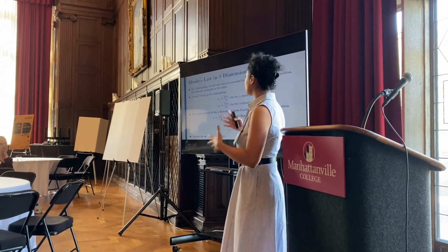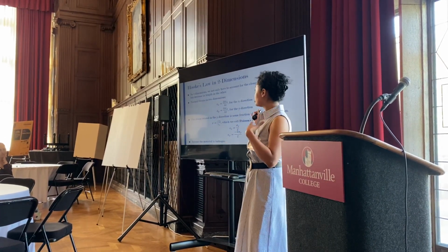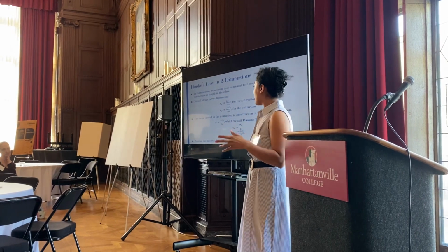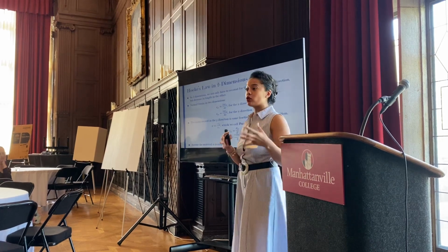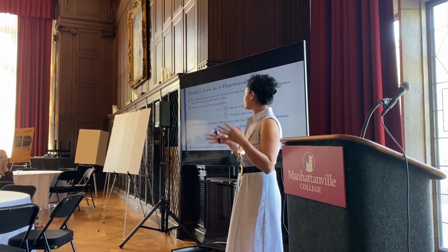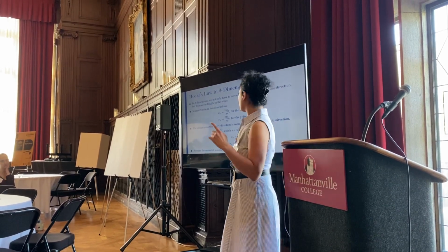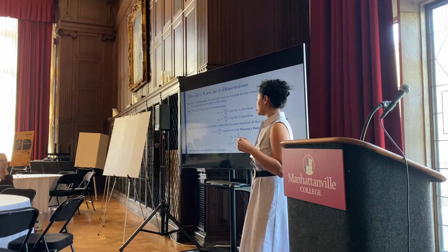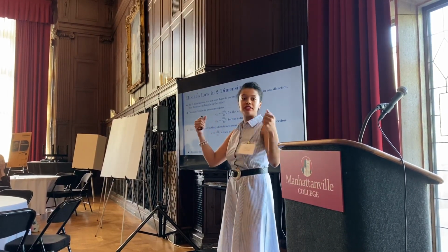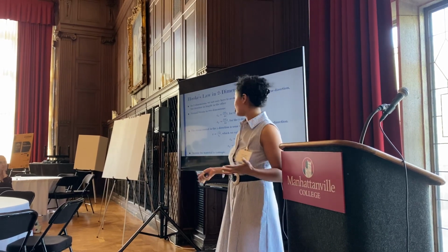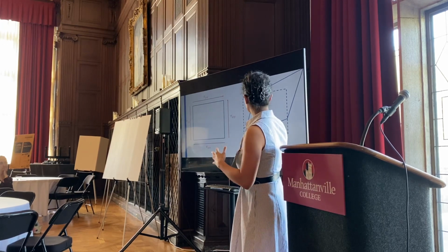In the second dimension, it works in the same manner. You just take the change in the value of the certain direction you're looking at over the original value. The normal strain in the x direction and the y direction can be correlated using Poisson's ratio. Poisson's ratio is the other value we were changing in each of these trials. We are also assuming the material is isotropic. What that means is if you pull it in one direction, it is going to behave in a certain manner. If you pull it in the other direction, it is going to behave in the same manner. This is an example of skewing, which I will talk about on the other page.